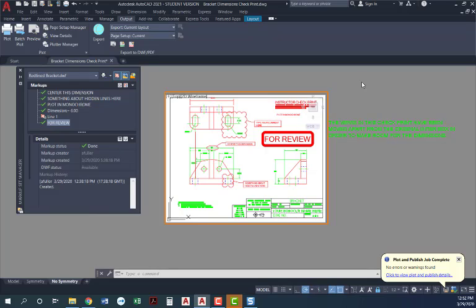So you can see here, AutoCAD can do a PDF, but doing it as a DWF is actually a lot more powerful. It's a really great way to communicate back and forth while you're in school, and submit your projects electronically with your instructor. But if you were working in a job environment, imagine how much paper you're going to save, where you don't have to print out 10 sheets for that one project. You just make one 10-page DWF, send it off, they mark it up electronically, send it back to you. This is actually a really great way for companies to streamline their red lines and save money in the process.